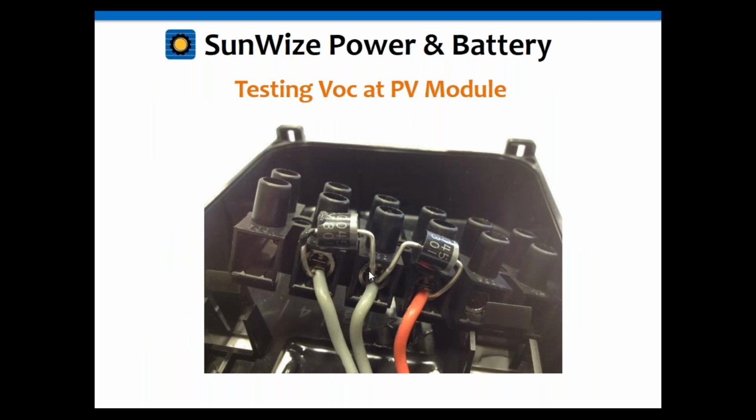Okay, and this is a great example of the diodes I was talking about earlier. These can actually be removed and tested. These wires here, again, I had a call where one of these was loose. I forget which one it was, but one of these got loose for whatever reason over thermal cycling. So these are things that you'll want to check inside the junction box if you're having issues.